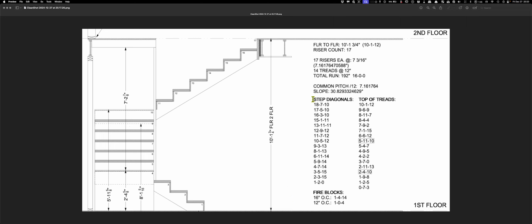So it worked out really nice. So just by doing the math, I know that pre-cut 9-foot studs are 104 5/8 plus 4.5 inches worth of plates plus 11 7/8 I-joist plus 3/4 subfloor. And that's that magic number right there.